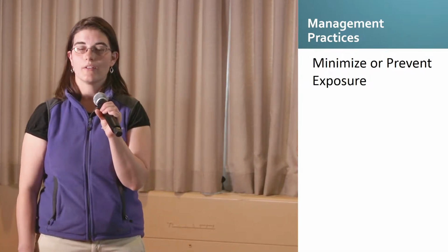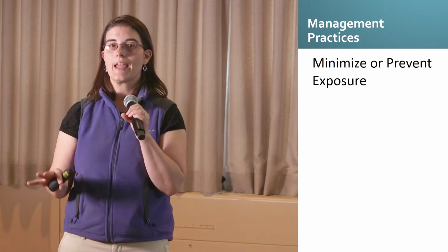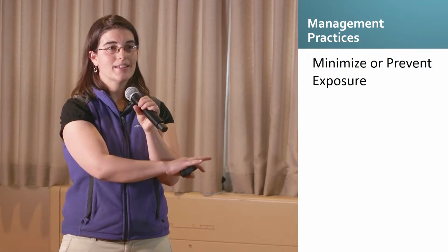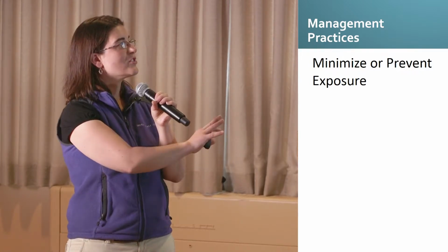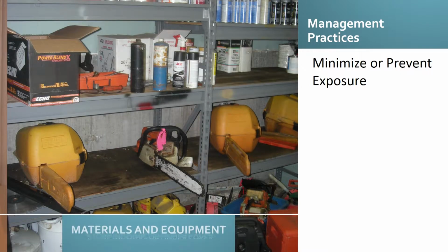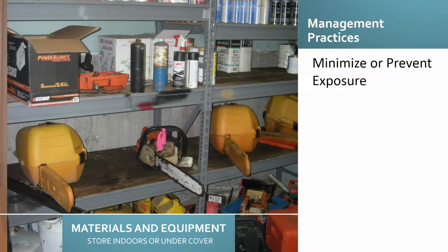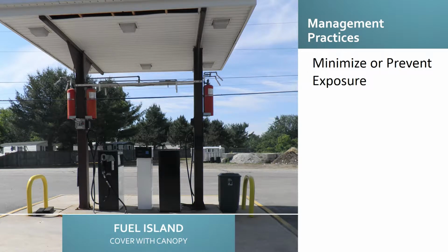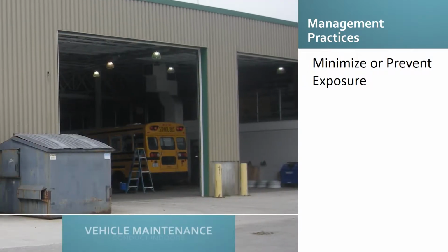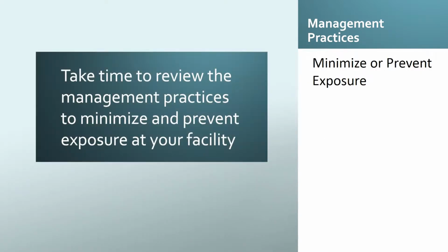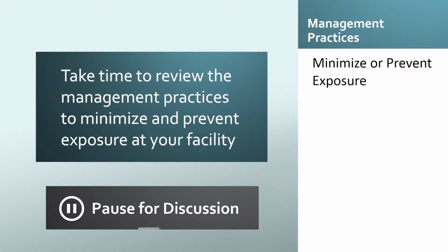So here are a few examples. And again, these are examples. These are not specific requirements. The management practices are the requirements, and these are just examples of ways that you can meet those requirements. So under minimize or prevent exposure, you could store materials inside and under cover. You could cover your fuel island with a canopy and conduct all your vehicle maintenance indoors. Take time to review the management practices to minimize and prevent exposure at your facility.